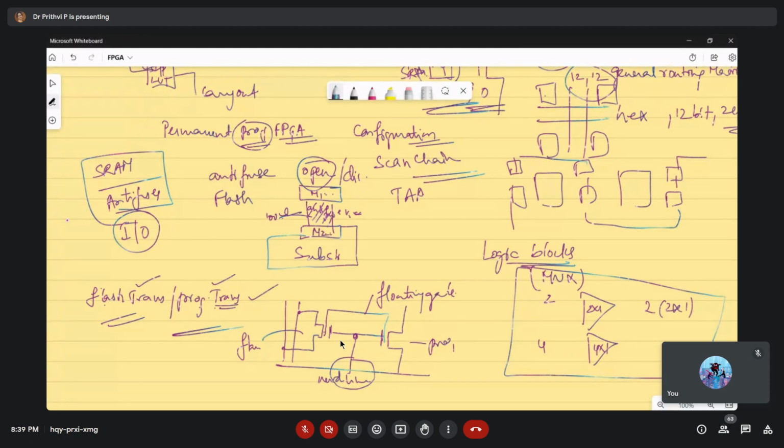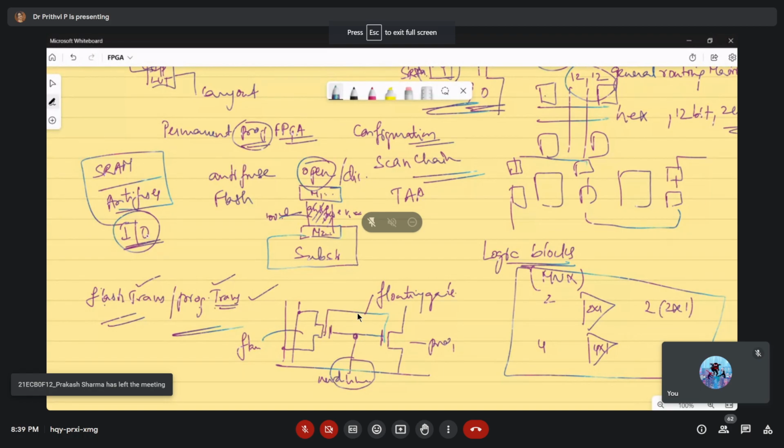Okay, when you are defining these input output pins, what has to be incorporated is that they should be electrostatic discharge protected pins. They should be acting as buffers. Output pins should act as a buffer with sufficient drive to produce sufficient signals to drive the next stage to which they are connecting.